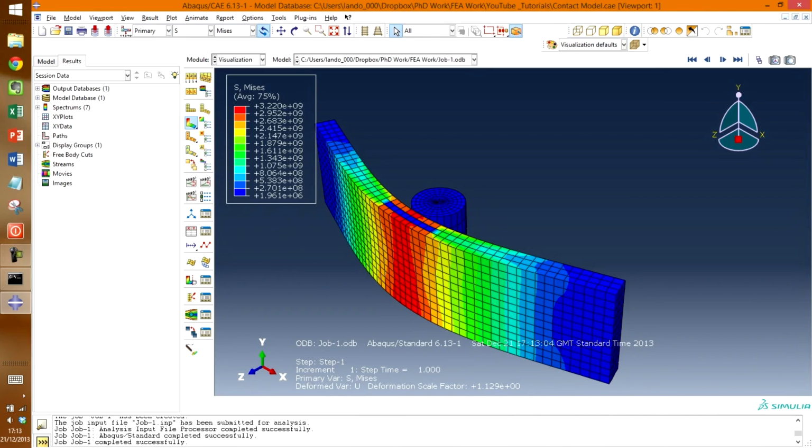Today we're going to be looking at creating a 3-point bend in Abaqus. I'm using this pin to apply a load and then showing you how to extract the load and displacement data to develop that curve. To simplify this particular example, I'm going to be using a boundary constraint to define the support pins on the exterior of the specimen, and then we're going to be initiating a contact constraint between the pin and the surface of the specimen, just so that the specimen deforms correctly around the pin.